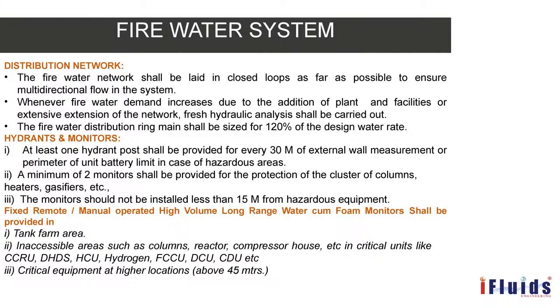And whenever firewater demand increases, then you have to perform the hydraulic analysis, to determine whether your distribution network is adequate or not. So whenever you are going for a modification or expansion in your facility, then you have to perform a hydraulic analysis to check the adequacy of the existing distribution network.